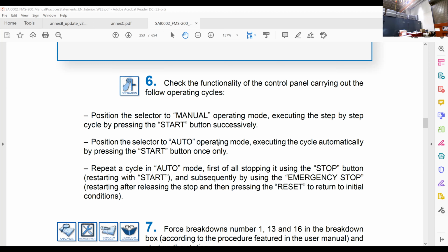So each station has a set of logic to it that's initiated like 10, 30, 40, and so on. Whatever section you have problems with, these numbers are going to tell you where to go in the PLC program to get you in the ballpark of the problem. They're going to put you right on point. Once you get in the PLC program, you will go, for instance, to the area starting with 70 and following if you've got issues with this evacuator.